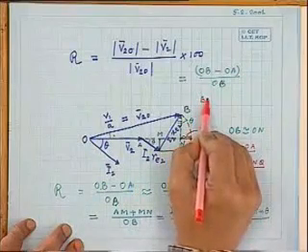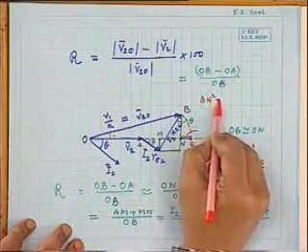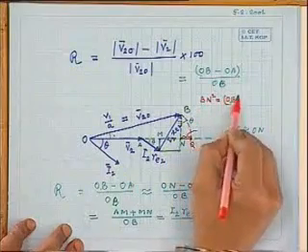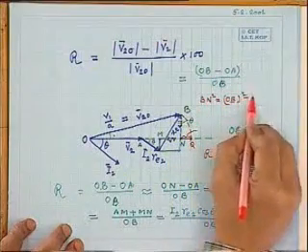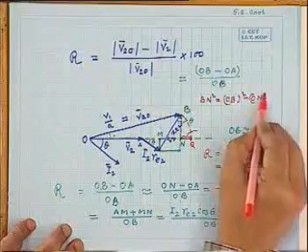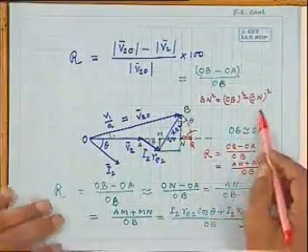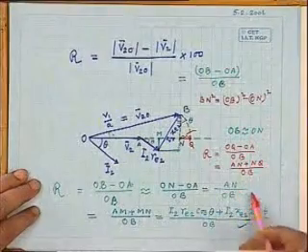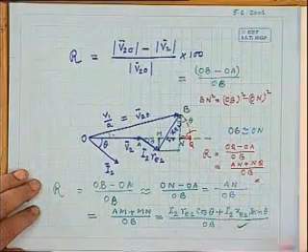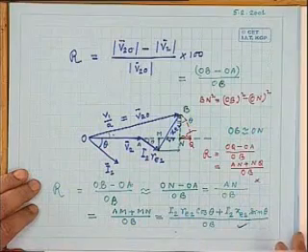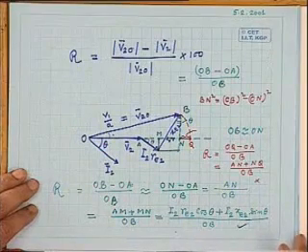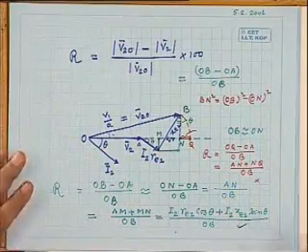That can be done by this right angle triangle. From this right angle triangle, you know that BN squared is equal to OB squared minus ON squared. So in this way, try to find out whether you can get another additional term and get a further better result for regulation. Of course, for all practical purposes, we will be happy to use this regulation formula.